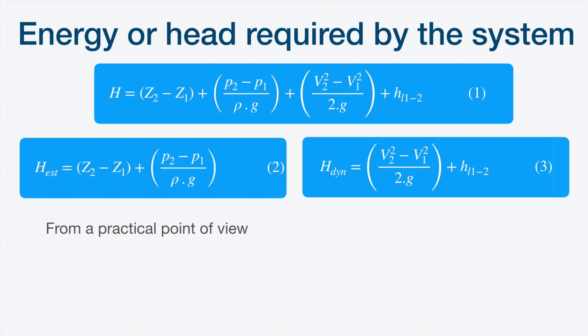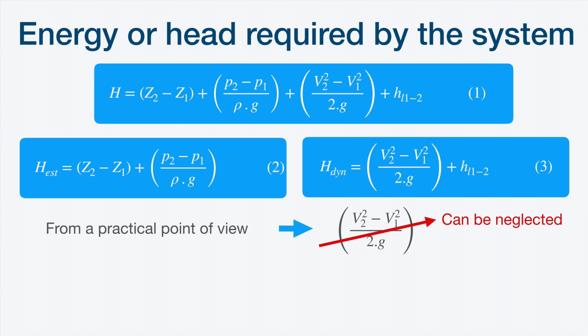From a practical point of view, this term, the velocity head, the kinetic energy, can be neglected. It is a very small value, close to 0. It is not significant, so we can neglect it.